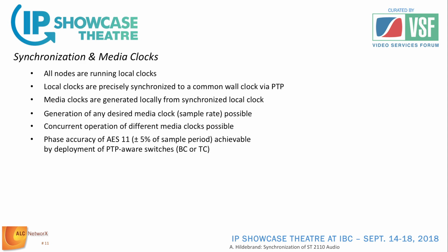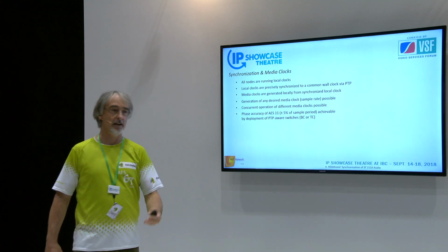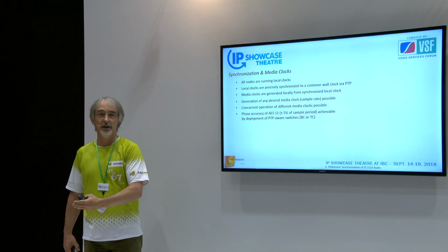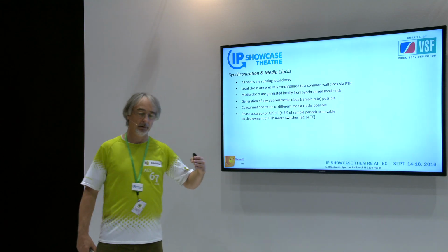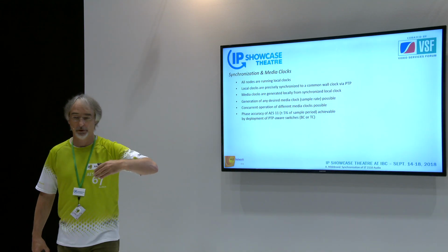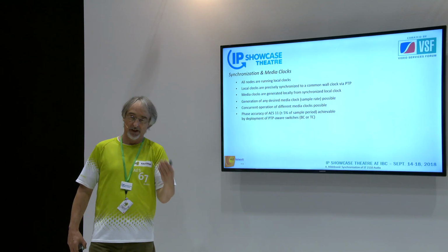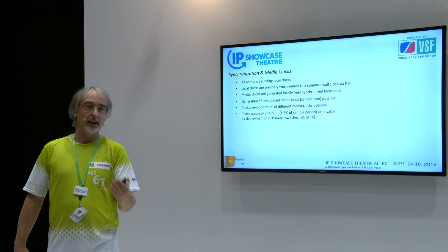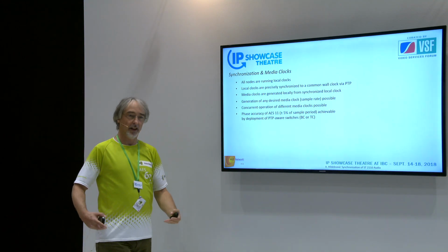In some cases, that would require PTP-aware switches. PTP-aware switches are those switches which natively can identify PTP packets on a network and can correct any residence or transport duration within the switches, so they add an offset value to the timestamp of the PTP packet in order to tell the downstream devices how long that packet had been resident in the switch.